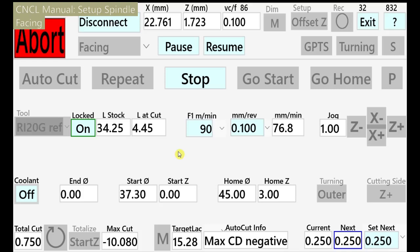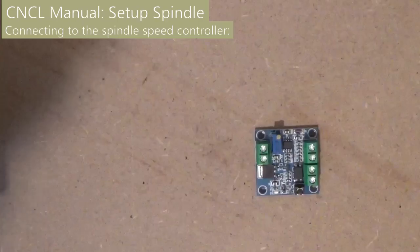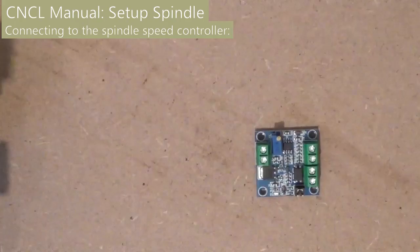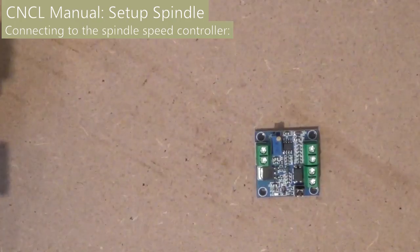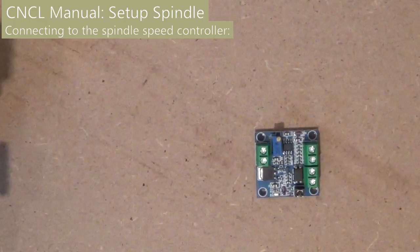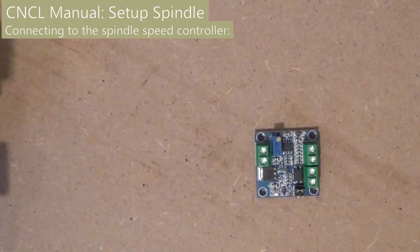In general, to get a repeatable result, I run the spindle in speed mode and the feed in feed per revolution mode. To use spindle speed control, you have to connect the CNC controller's spindle speed output to your lathe spindle speed controller input.